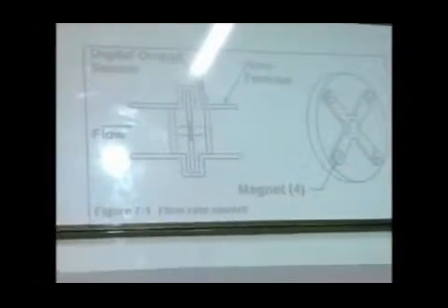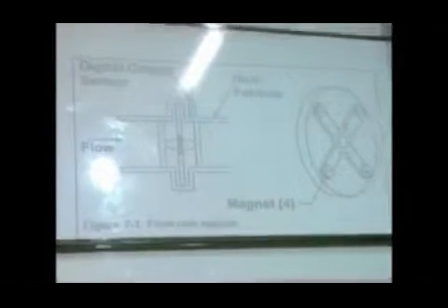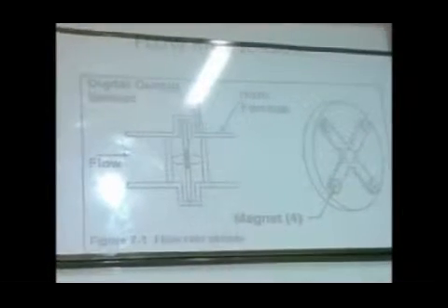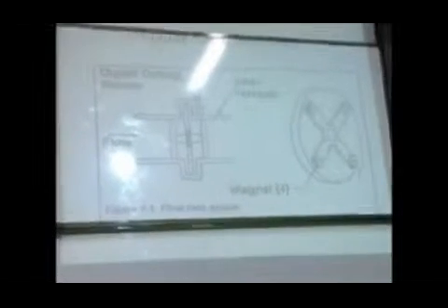In this design, the softener can be made to automatically recharge on demand instead of on a timed basis. The demand is determined by measuring the amount of water that has passed, and when a certain level is reached, the recharge cycle starts. You can see it in the figure.